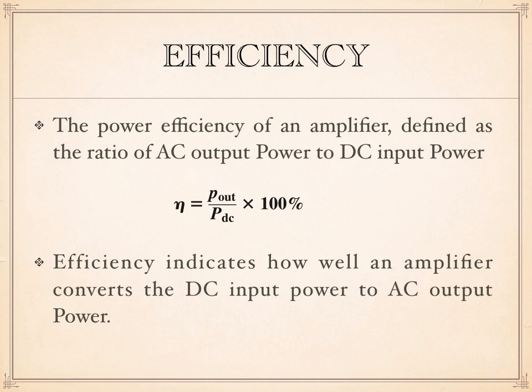As we know that amplifiers give high AC output for low AC input. We know that energy can neither be created nor destroyed. Then from where did this transistor get energy to increase the output level? Well, the transistor gets this energy from DC supply to boost the output signal, and thus more the efficiency, more is the DC power converted to AC output. Efficiency improves when we go from class A to class D amplifier.